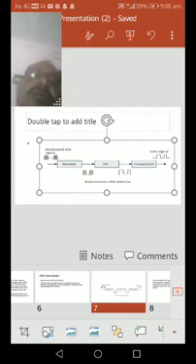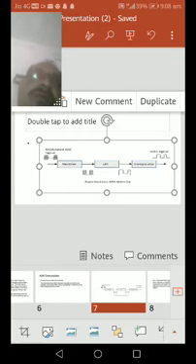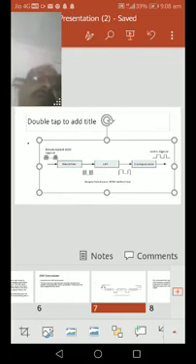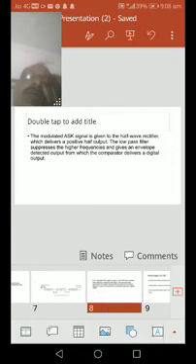Similarly, the sequence of bits coming from the ASK modulator is rectified and then given to the low pass filter. The low pass filter allows only low frequency components; high frequency components are rejected. Then it is given to the comparator. By comparing the values, we finally get the original information, the binary data signal.